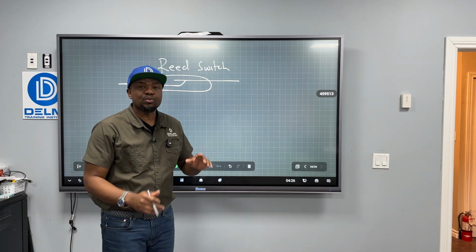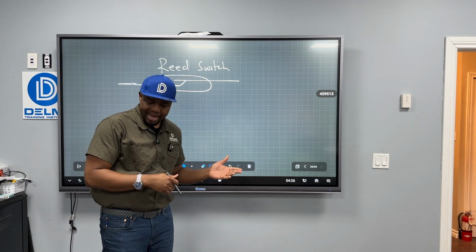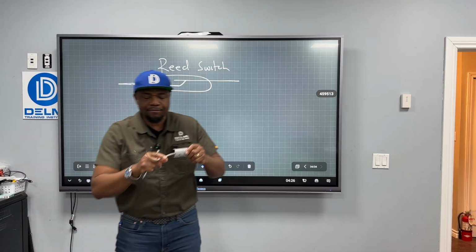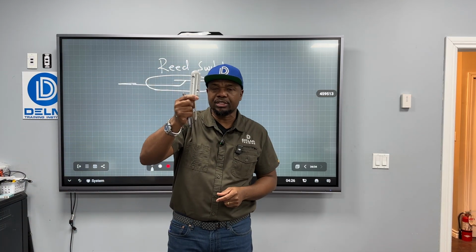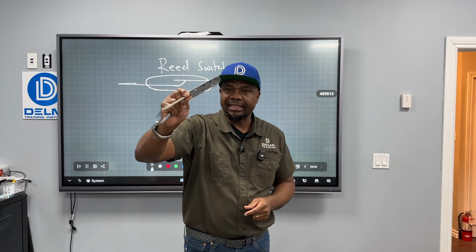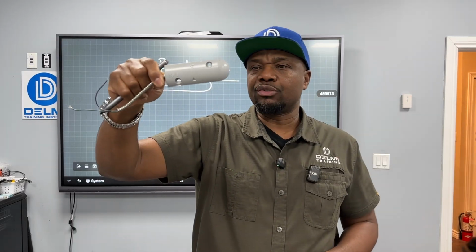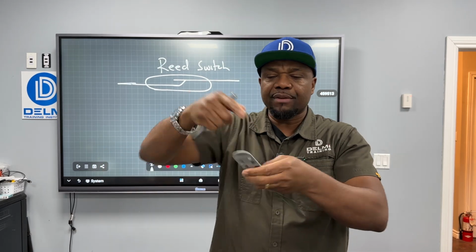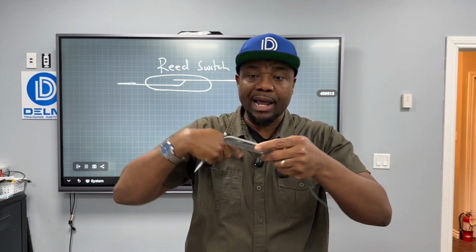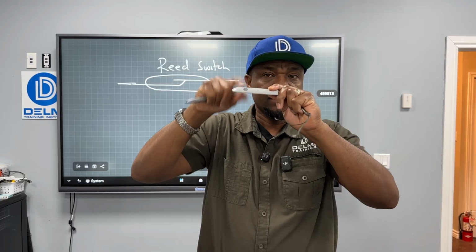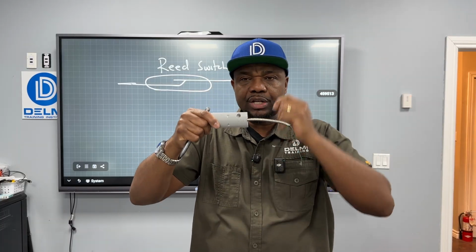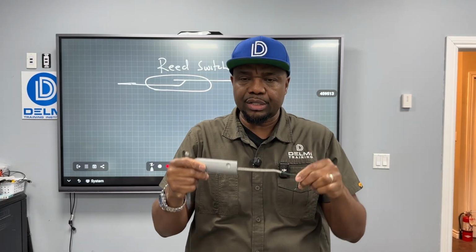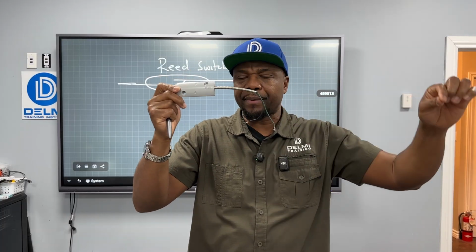On the other hand, these ones come in very diverse formats. You can have one that is an industrial switch, something like this. They use them in a lot of commercial spaces. When you have an overhead door that you want to monitor, you can directly bolt this to the floor, and the forklifts or the trucks can drive over it. Nothing is going to happen. So if you're doing any work in the warehouse and you need to monitor the door, you can put one of these. It comes with a long pigtail.